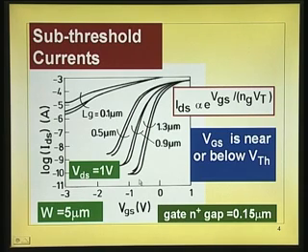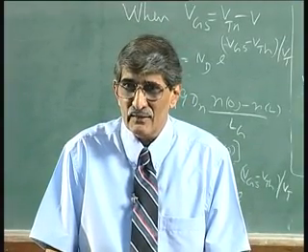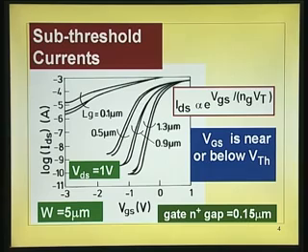Okay. Now, there are several curves which are put depending upon the channel thickness, channel length. One thing, your threshold voltage itself changes as you reduce the channel length. That we have seen, your two dimensional effect, the change in threshold voltage. Okay. Why should this slope change?